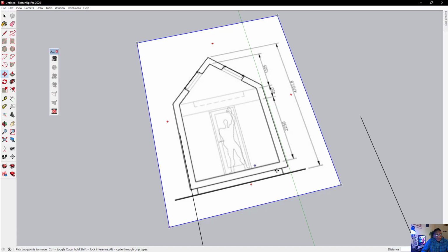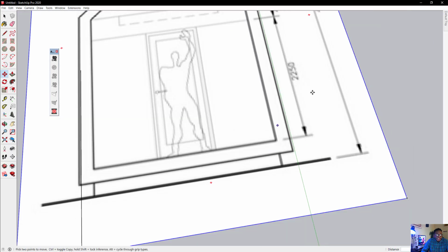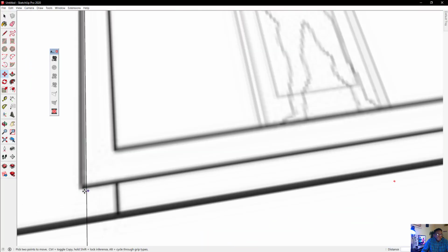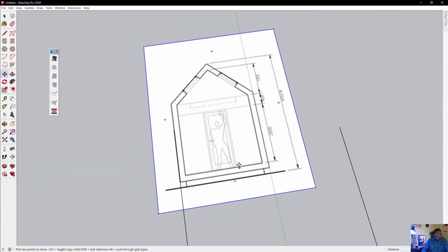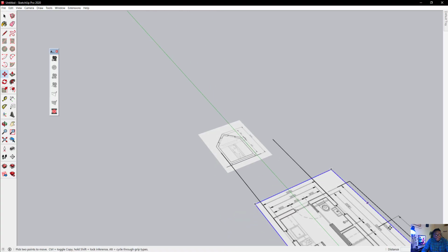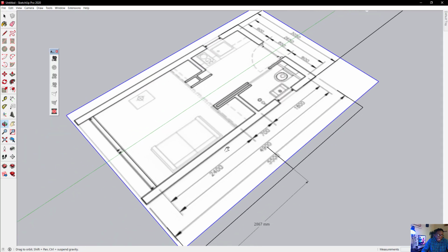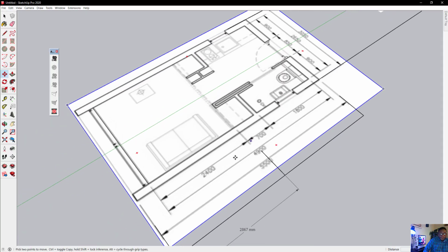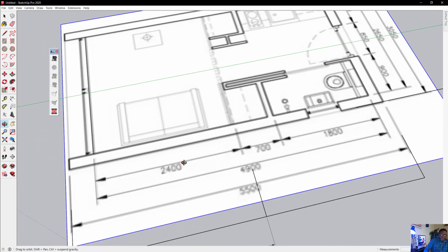And this is the point that I wanted to get to. The dimensions are more important than what you eyeball. Let me repeat. The dimensions that you do here are more important than what you eyeball, right? So for example, let's say you're going to draw this wall here, and this wall must equal 5,500.